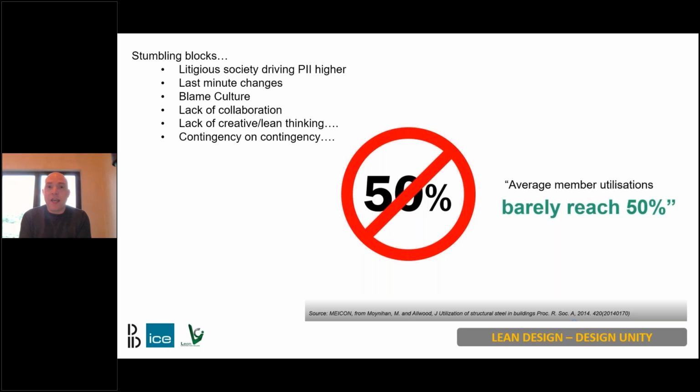That's really quite a level of over design. There are lots of things tied in with that. There's contingency. Again, there's the over specification of floor loads as well. So that's a big focus for us, to make sure that we're designing as best we can to a unity of one, getting the design capacity of the element as close to the actual load that's going into it.